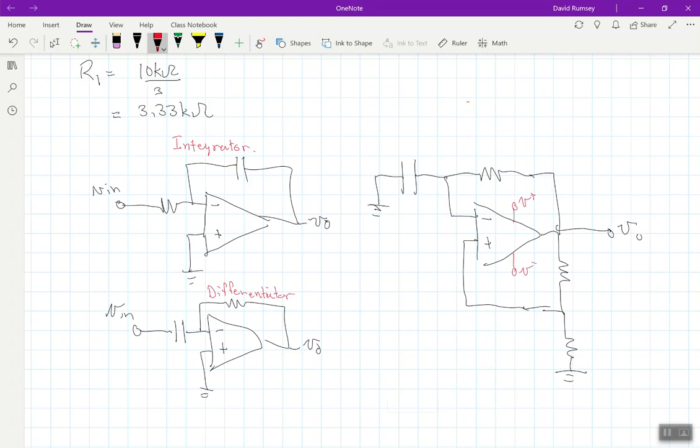And believe it or not, this simple circuit, choosing appropriate values for R1, R2, and so on, I know I haven't labeled them, but choosing appropriate values for these resistors and capacitors, this is actually a square wave generator. You can generate a square wave out of this, and you can generate it at a specific frequency, so you can generate a signal that looks like a square wave, just like this, coming off of this op-amp. So there's lots of different op-amp circuits, and this still doesn't even cover them all. Lots of different applications.